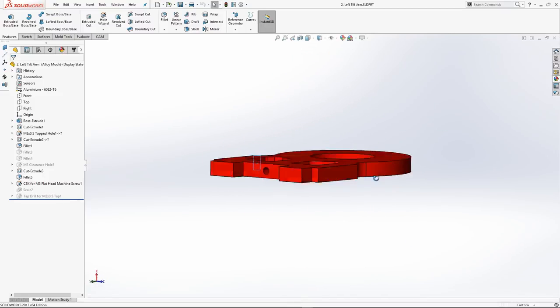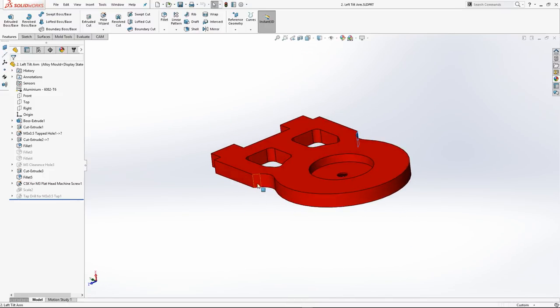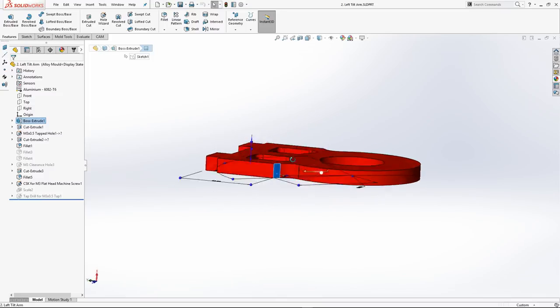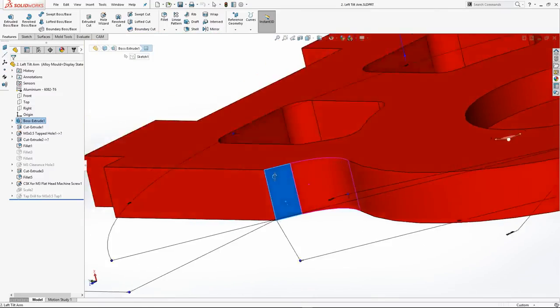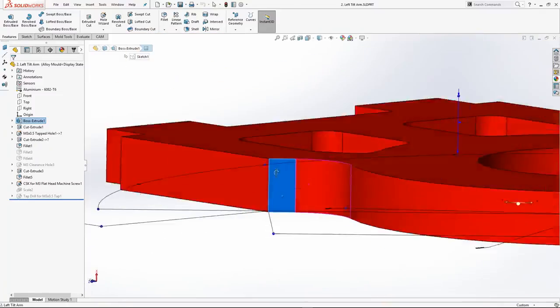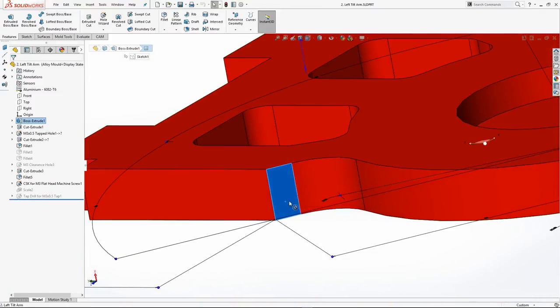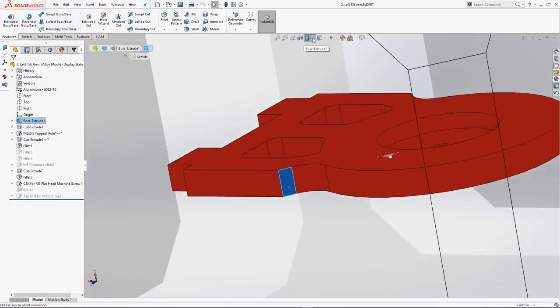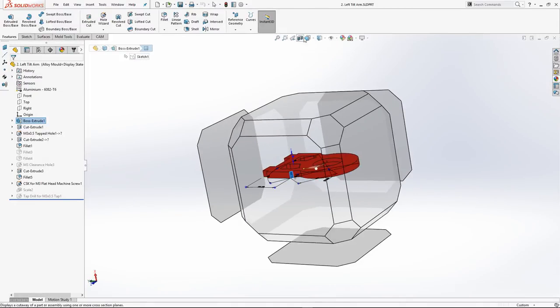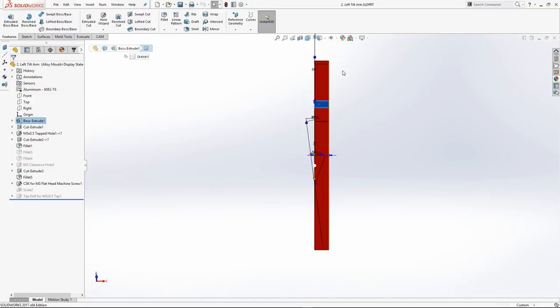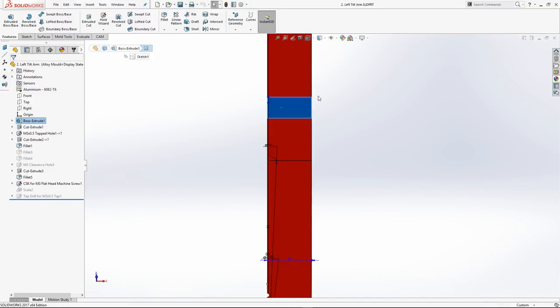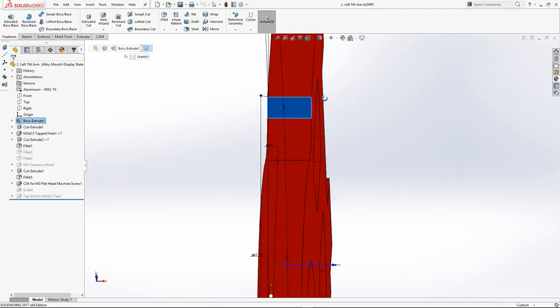If you want to design something, or you want to do an extrude on this face, for instance, it can be a bit of a nightmare to get it in the orientation that you want when you're doing the sketch. What you can do is click the face you want the view on, and then click this little button here, and it'll bring you on that face, so you're actually looking directly at it.